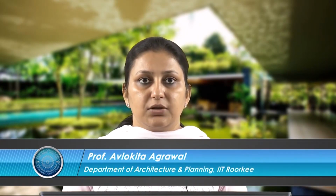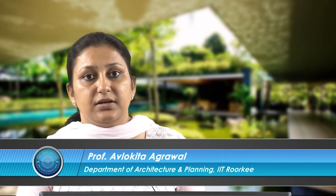Good morning. Welcome to this lecture for the online course on sustainable architecture. In the previous lecture, we were discussing the tools for understanding the response of the building to the given climatic context. There we talked about the bioclimatic chart, and we learned how to use Mahoney's table to identify the appropriate design strategies for the given climatic context, based upon the understanding of air temperatures, humidity, rainfall and wind data.